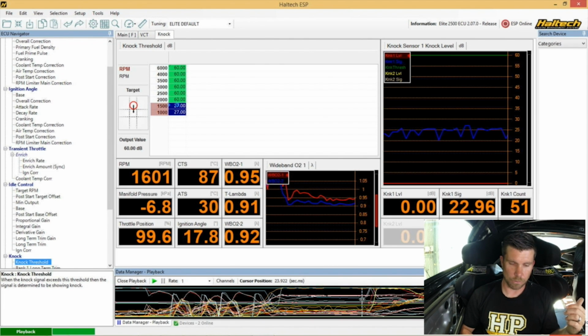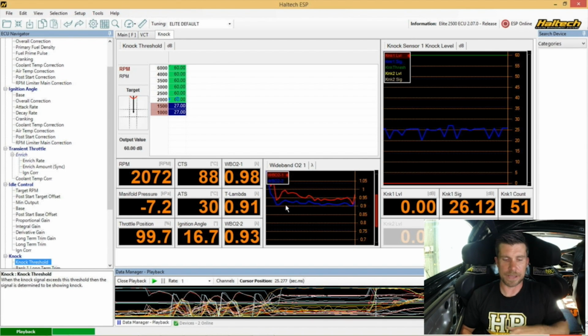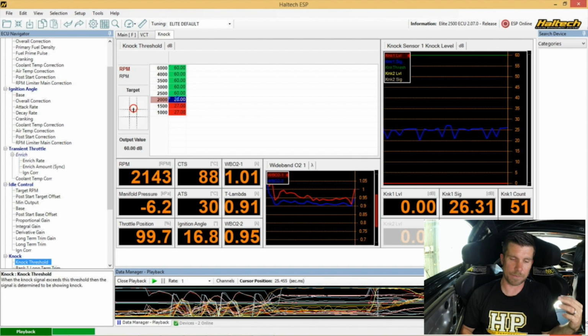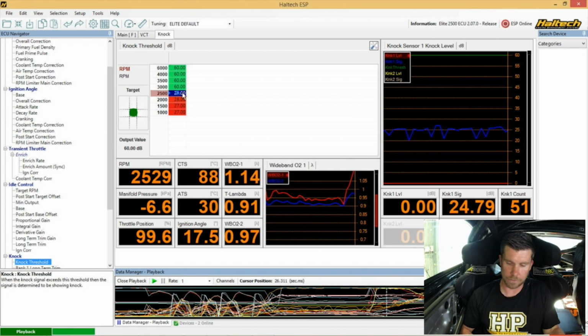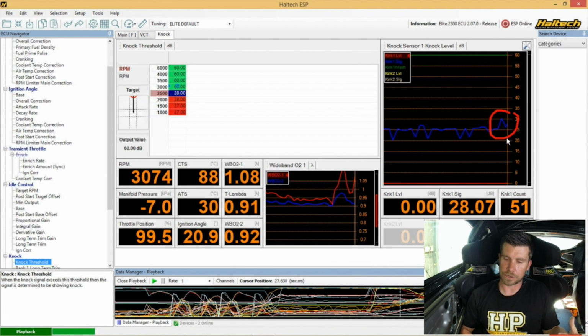27. Once we've done that, we'll move through to the next point, which is 2000 RPM, and at 2000 RPM we're seeing approximately the same noise level, perhaps just a little bit higher. We don't really need to be super accurate right now, because we will do another run and confirm exactly how accurate this is all working out. So I'm just moving through the RPM now and increasing. You can see now we're up to 3000 RPM, and we've got a little spike there that just sits on about 30, so we'll go a little bit higher than that.